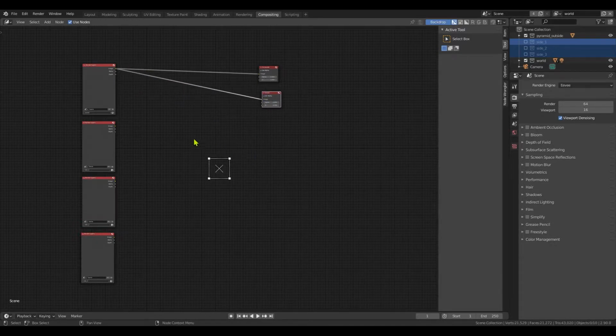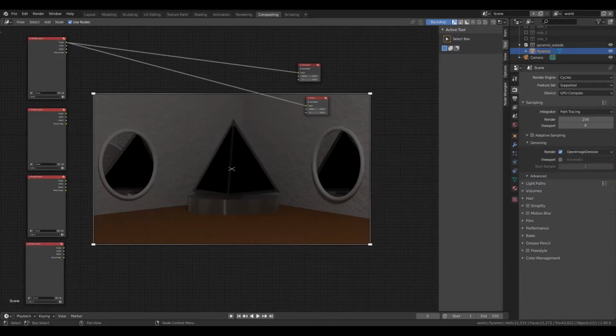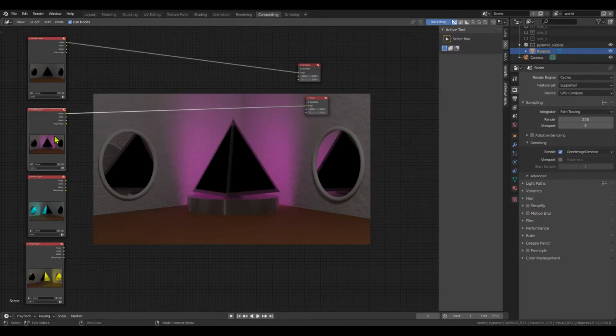As you can see, the render layers node does not have an output yet, because we haven't rendered anything. With F12, we can fix this. After rendering, you should now see the image of the viewer in the background, and all render layers nodes should produce an output. You can verify this with Shift-Control left-click on any of these nodes. Apparently, changing any of these connections also adds the previews of these nodes.